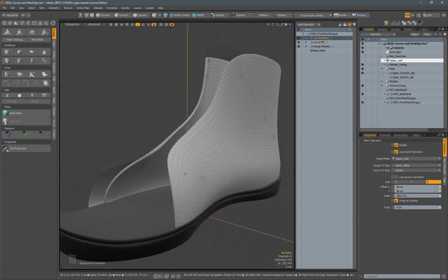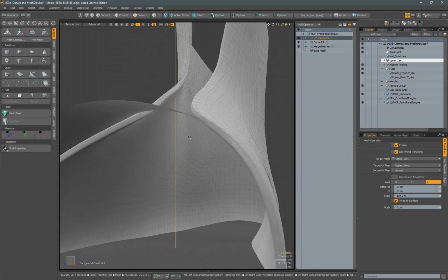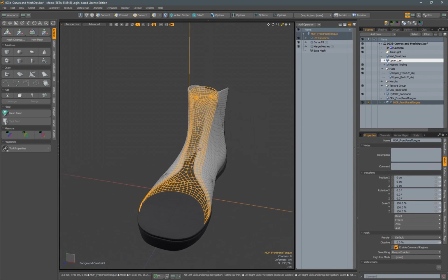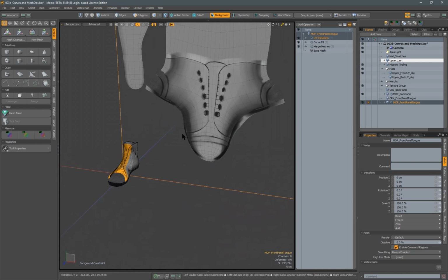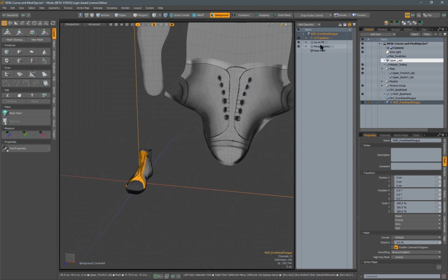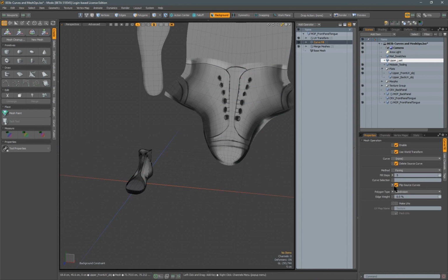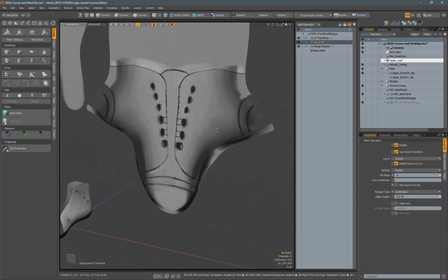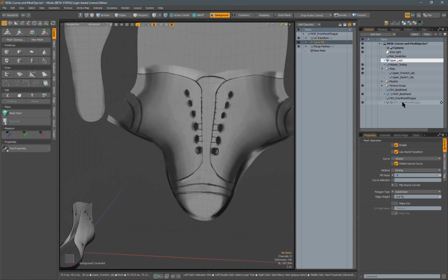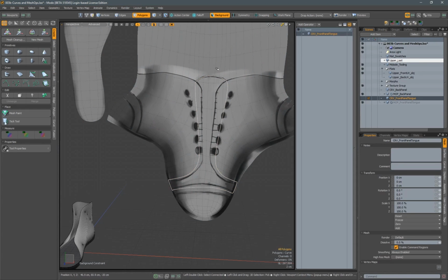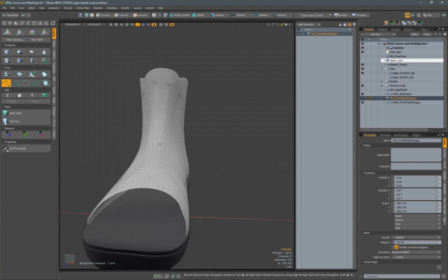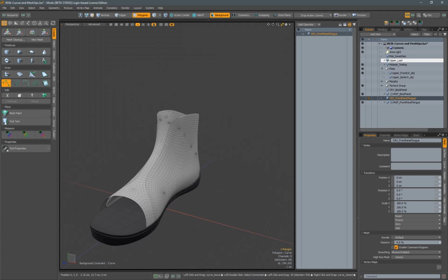And you can see that our mesh is filling in. But because we flipped it, it's actually facing inward. So we got another option here that we can change. And if we go back to the flip source curve, it disappears because the source curve wants it to be facing the other way. So let's go back to the original curve. Go into poly mode, then hit F for flip. And you can see right away that it's facing the right direction, and it's also populating on top